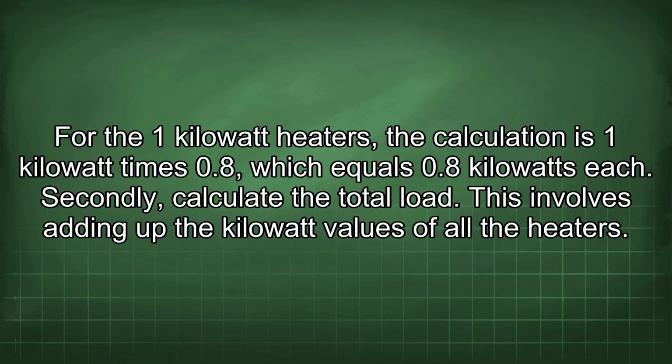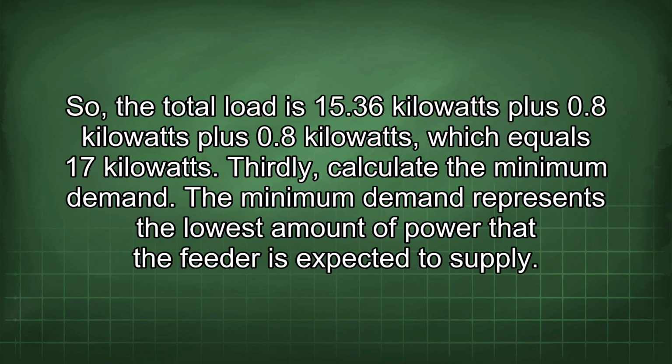Secondly, calculate the total load. This involves adding up the kilowatt values of all the heaters. So, the total load is 15.36 kilowatts plus 0.8 kilowatts plus 0.8 kilowatts, which equals 17 kilowatts.